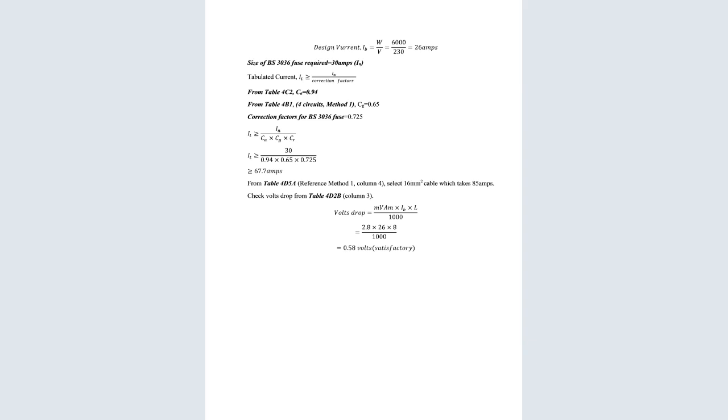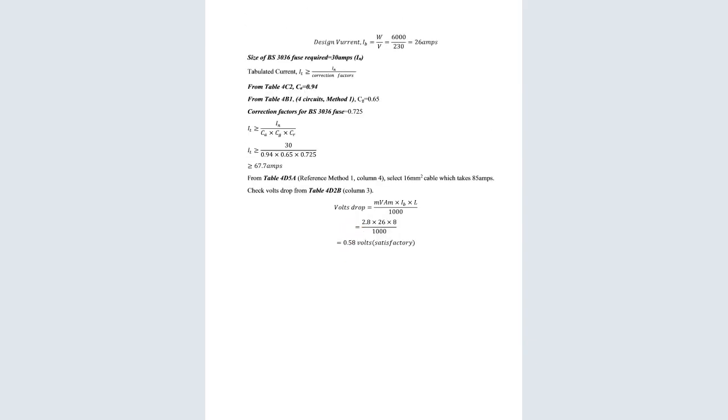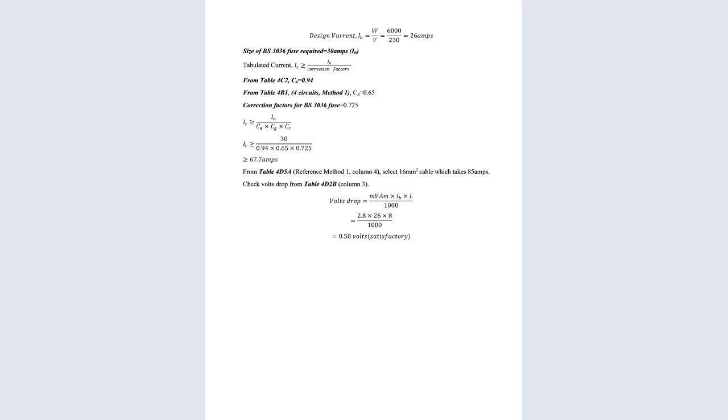So you normally equate this current loading to the BS, the standard. These BS standards are normally given, and they are there for any calculations, and they are codes of insulation that are normally given. That table is normally given, so in case of an exam, you will be supplied the table so that you can calculate.